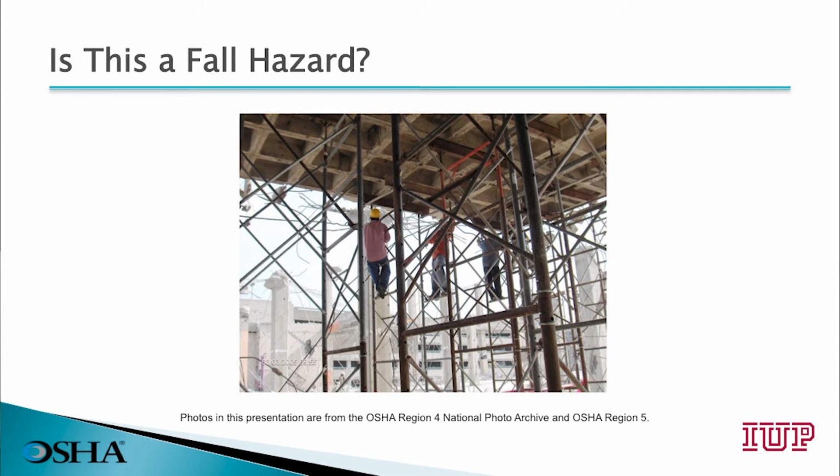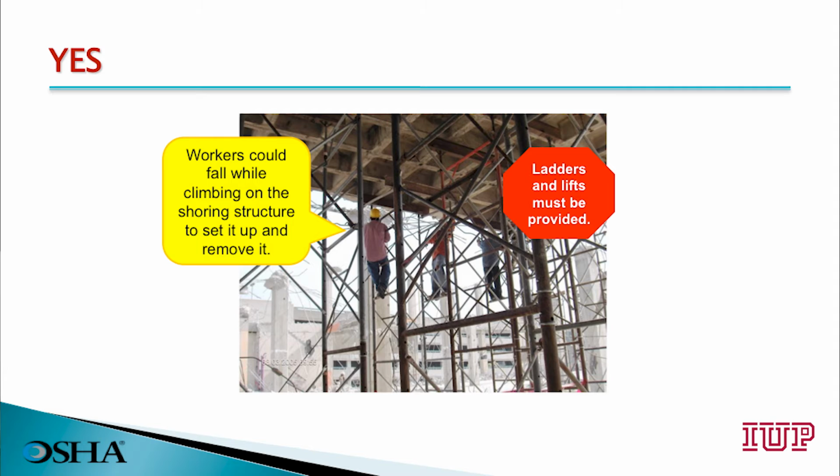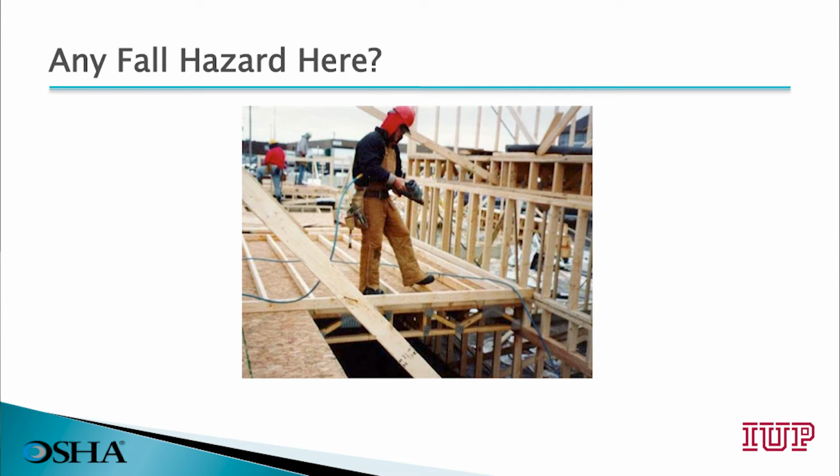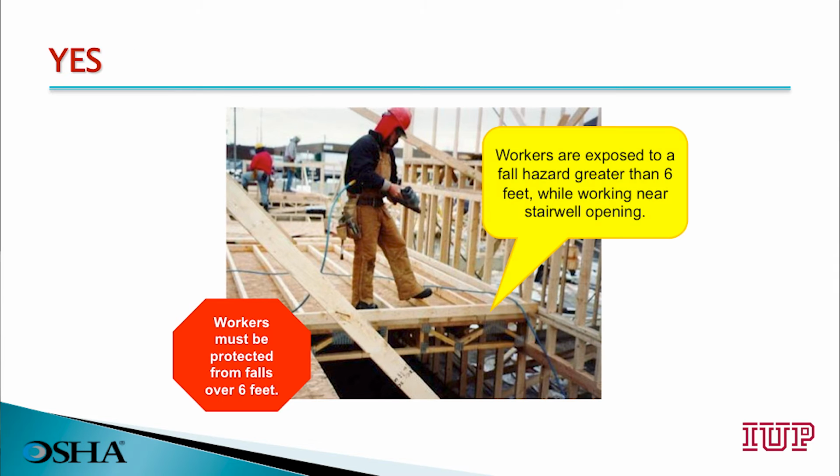Is this a fall hazard? Yes. Workers could fall while climbing on the shoring structure to set it up and remove it. We should be providing ladders and lifts. Is there a hazard here? Yes. Workers are exposed to a fall hazard greater than 6 feet while working near this floor opening. Workers need to be protected from falls greater than 6 feet.